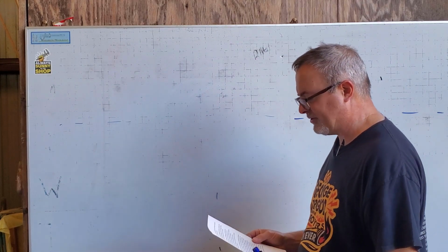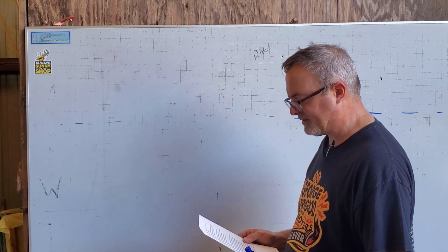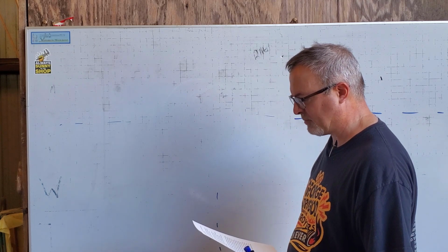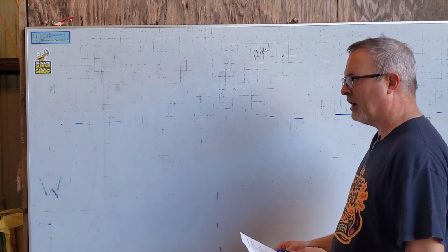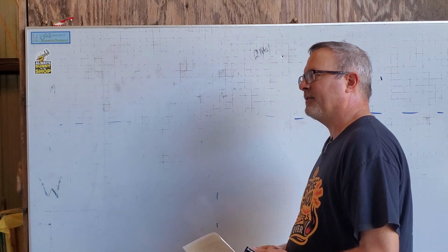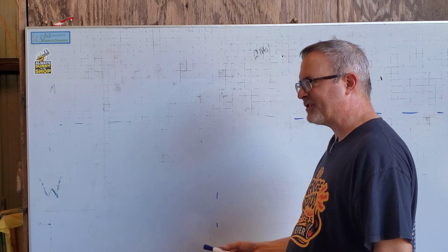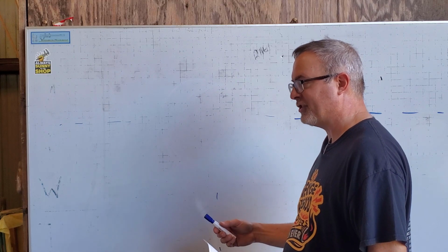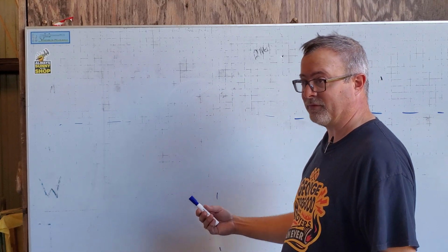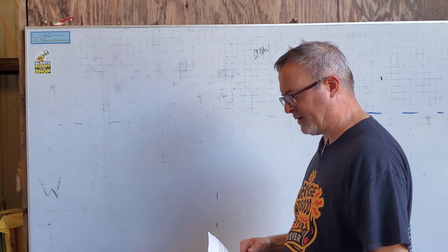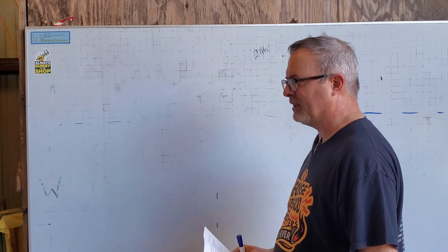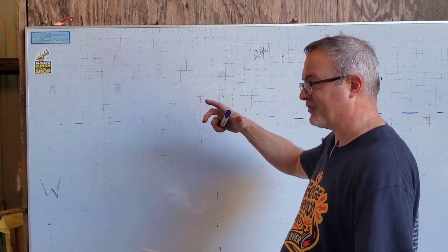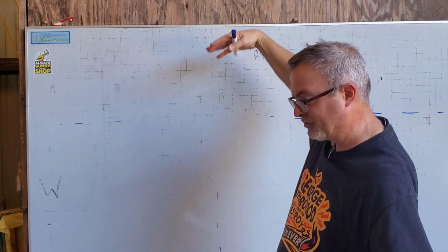Number 10, Porter greatly reduced the size of his flywheels from what was standard at the time because the larger flywheel would probably not survive rotating at 300 RPM, and because at 300 RPM a smaller flywheel could be used successfully. Semi-true. The energy that a flywheel stores increases proportional to the square of the speed, I believe. So the faster an engine turns, you can have a proportionally smaller flywheel and have an equal amount of variation in speed. Cast iron flywheels have a limit of about 5,000 surface feet per minute on the velocity of the rim to keep the stresses safe because the flywheel wants to stretch and burst as it's up to speed.